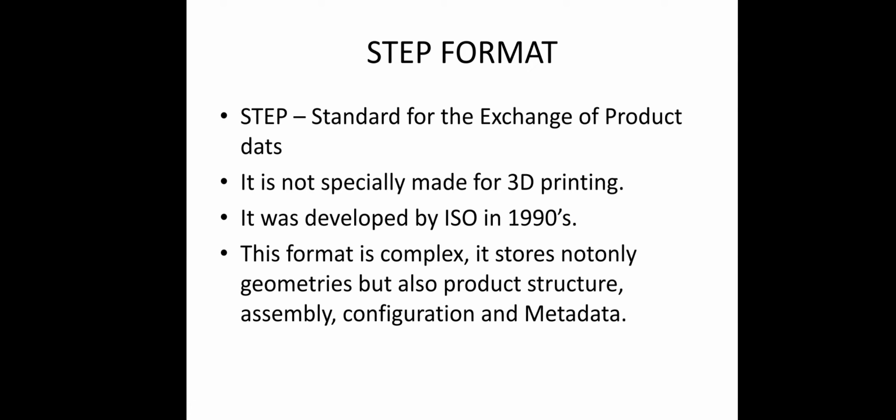And another format is the STEP format. STEP means Standard for the Exchange of Product Data, and it is a computer graphics standard format. It was not designed for additive manufacturing technology. It was designed as a CAD file format, and it contains product information.